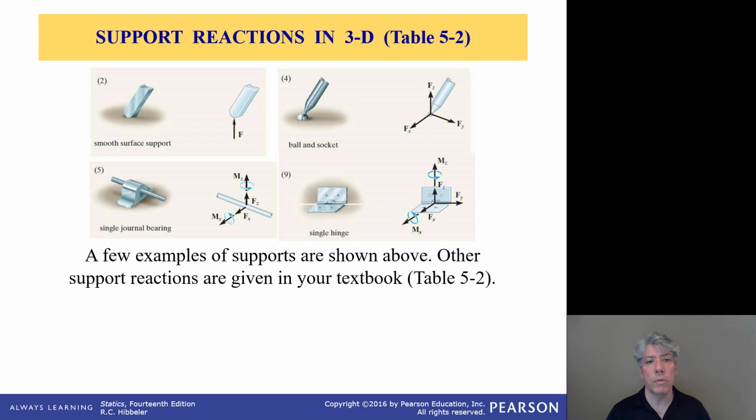But often when we analyze these situations, we consider it bad practice to have a bearing like this support a large moment load where the shaft is pivoting rather than just rotating. Also, even though there are, as I said, set screws to constrain the inner race of the bearing to the shaft, we don't assume that there's any significant force capacity of that interface and of the bearing.